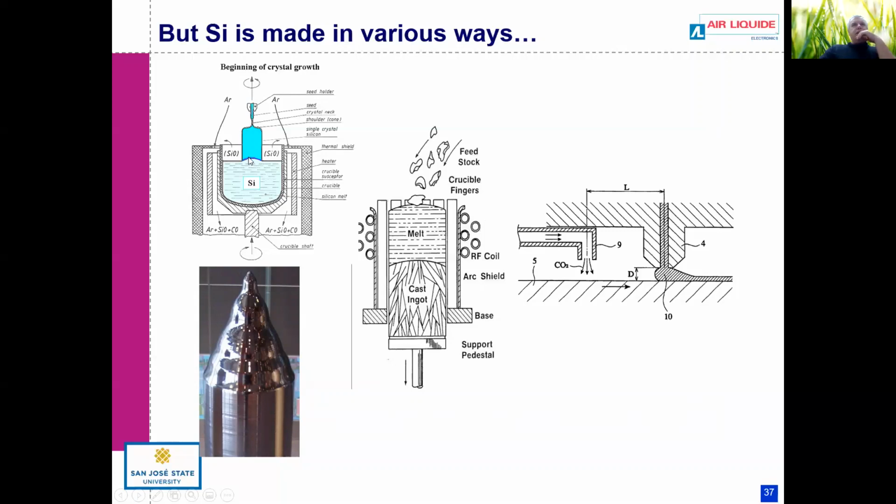You touch it to the top of the molten silicon here, and then you start to cool. You start to pull up on that wafer, and then what happens is that this is just right near its melting point, right? And the air around here is relatively cool. So from the point where the crystal touches it, that determines the crystal structure of all of this silicon that's condensing all around it, right?